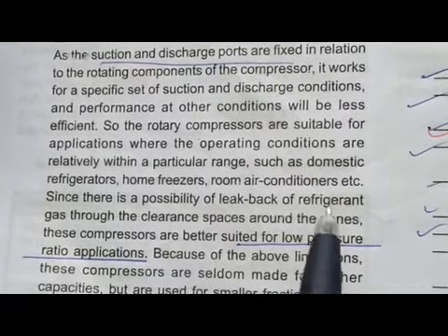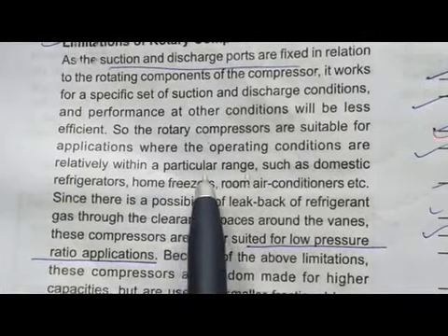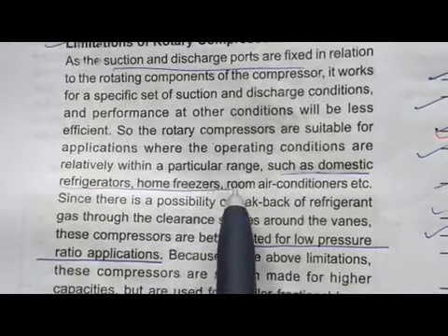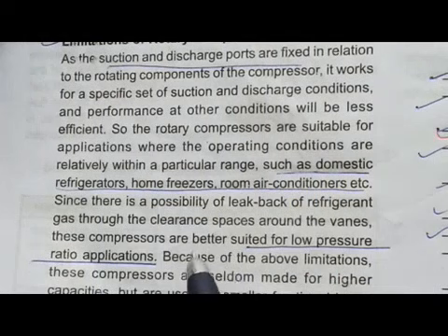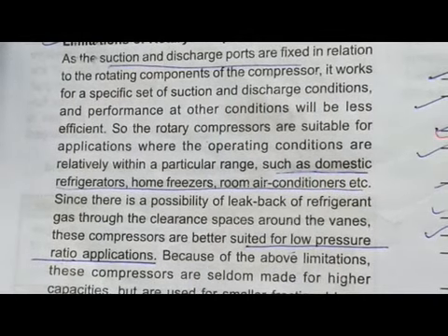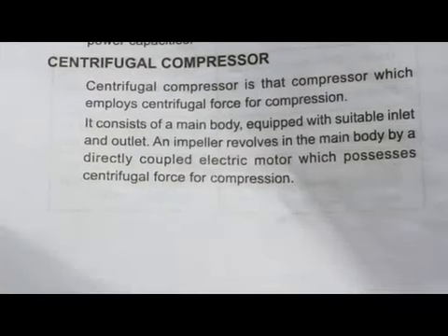Rotary compressors are suitable for applications where the operating conditions are within a particular range, such as domestic refrigerators and home freezers, room air conditioners, etc. It cannot be used for industrial or commercial purposes. It is suited for low pressure ratio applications. These are the disadvantages of the rotary compressor.